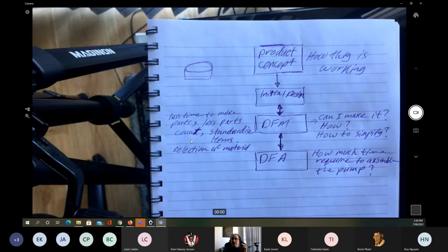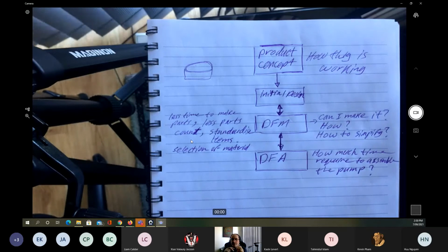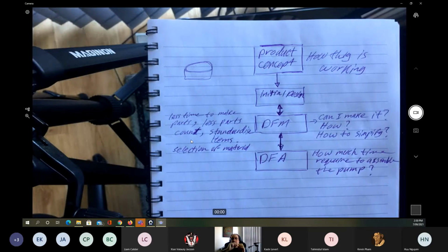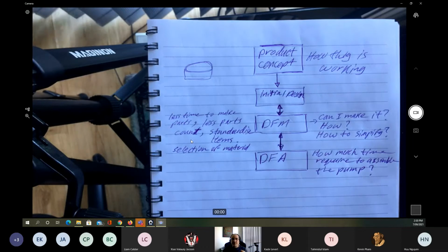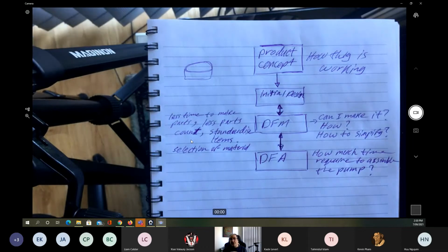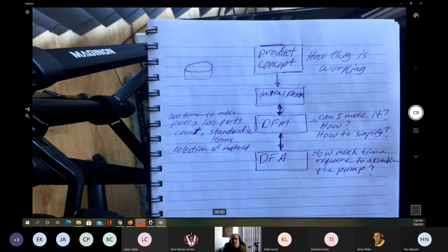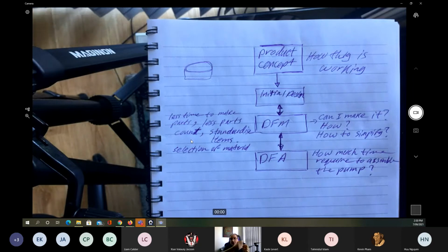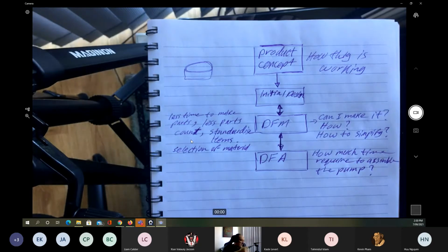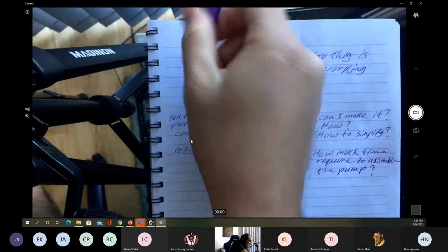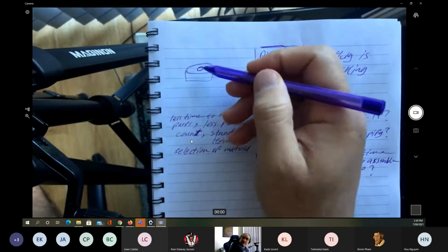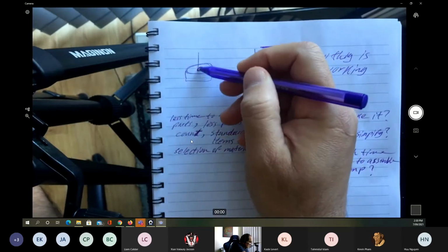For example, we're going to have nuts, and we have thread, and we said, okay, the time required to put the nut in position is going to be something about 5 seconds. I have 2 nuts, this will be 10 seconds. But in between them, I'm going to need to put the valve in the shaft. So actually, that's what will happen.